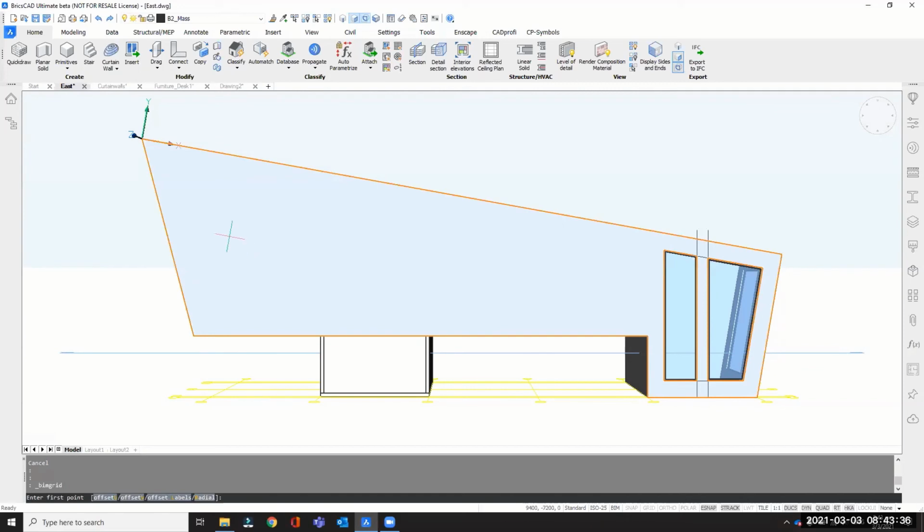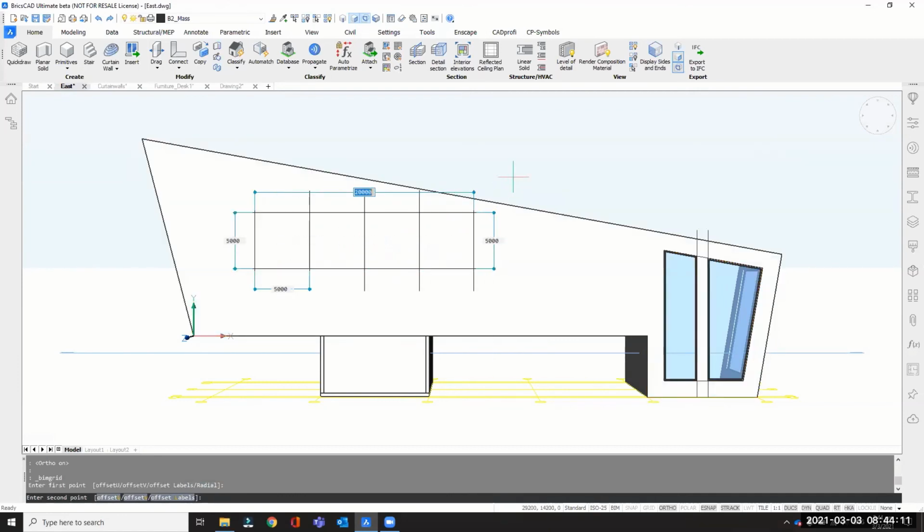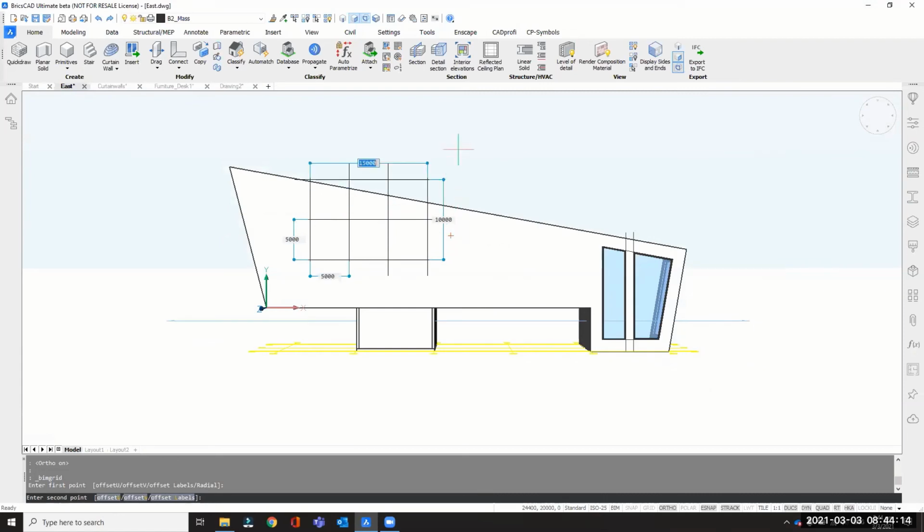Let's use this face. So if you see here, my cursor is actually following this point or this line direction. So how do I make sure that it's going to be following this part of my drawing? Just make sure you click ortho, and the grid will already be vertical or 90 degrees for us. So that's just one tip again. To lock this face, I can click on shift and it will be blue, meaning that it's already locked. My grid will be created on this certain face. So I just click there and I will see a grid.